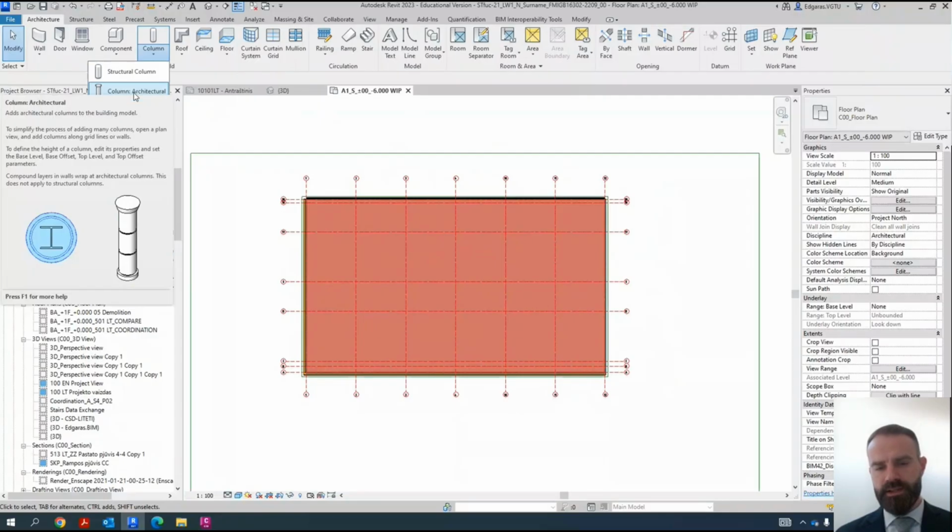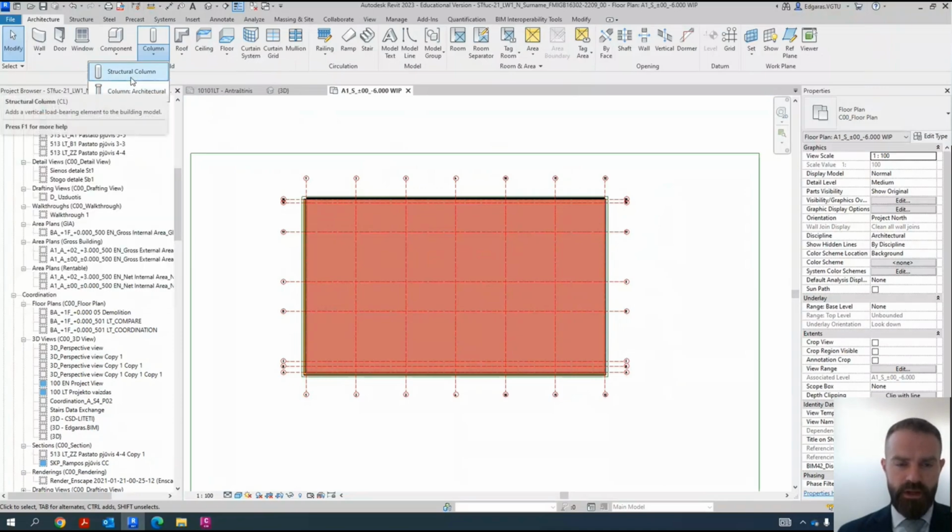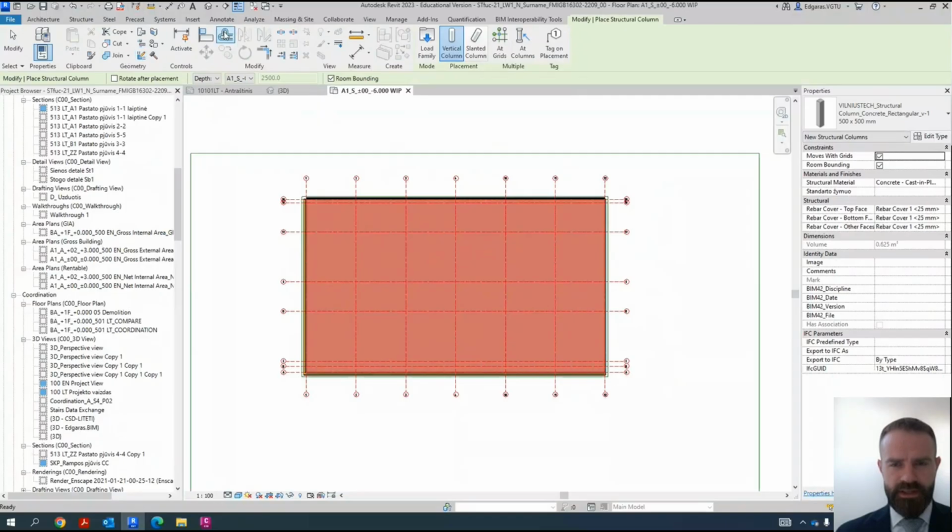So in the building site, first we build structure columns and later we put beautiful art pieces on top of the structure element. If you get architecture columns from the architect, you can replace them with structure columns, but normally in Revit practice, everybody is using structure columns in most cases. So let's select structure column.